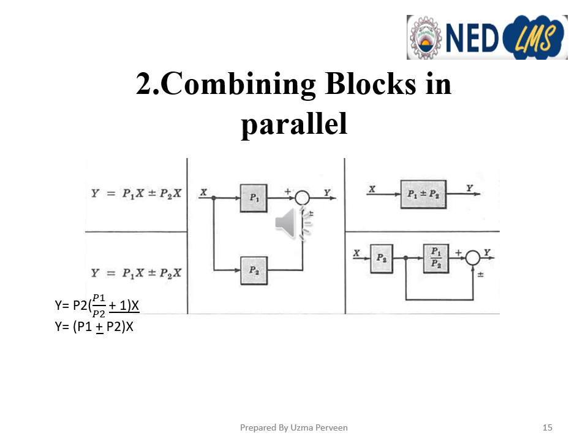Similarly, if we have this summer on the left hand side of the block diagram, usually it is a feedback path. We'll see that in the next transformation. So here this is actually a forward path again. The signal is y equals P1 x plus or minus P2 x. P2 is already here in series with the x, so it is P2 x.